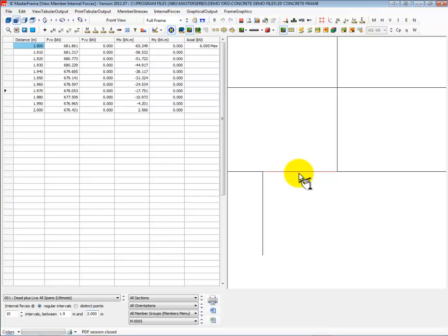If we were talking about our steel design, in designing our Appendix G out to the point of contraflexure, it's going to automatically know where that is for each loading case and do it. If we're talking about the concrete design, well, it knows what its envelope looks like anyway, and it designs to the envelope for curtailment. So all I can give you, Christoph, is a reasonably accurate approximation of where it is.